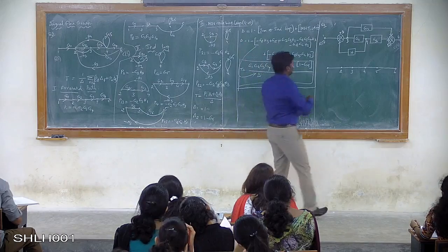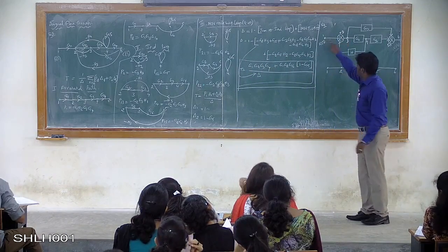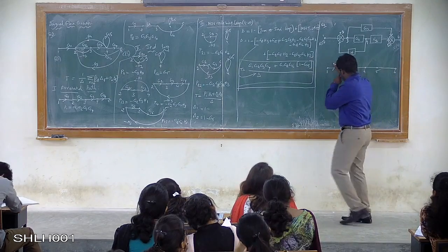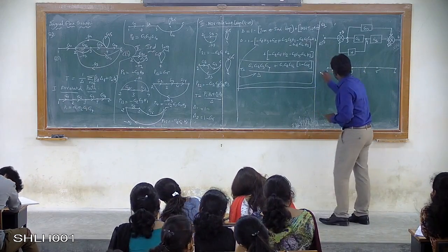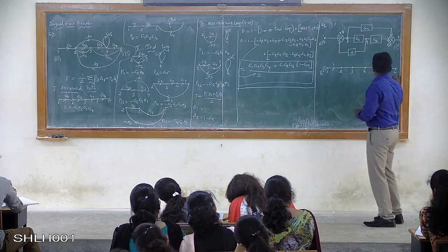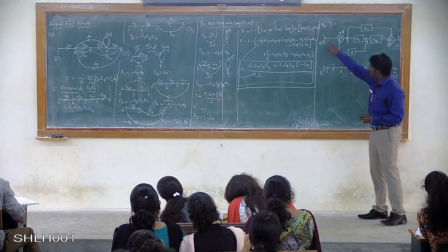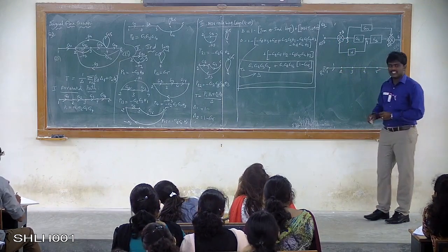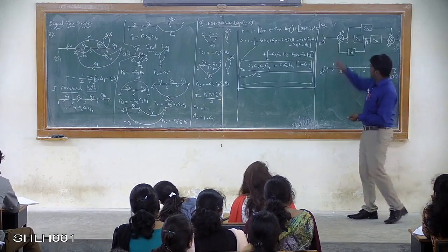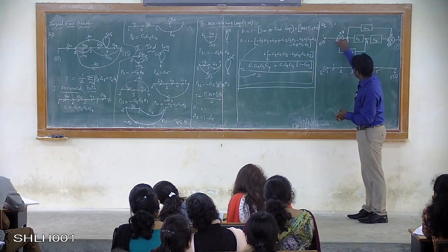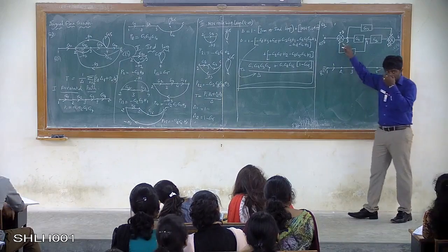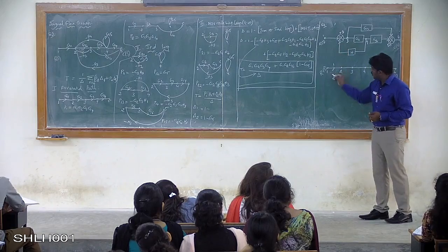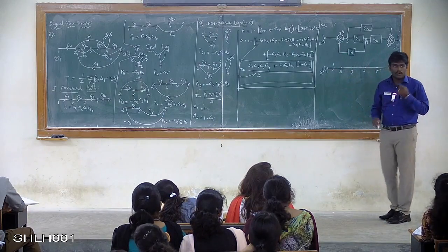Now, in between 1 and 2, right? What is the gain value? If anything is not given, you just take that gain value as 1. So this is R of S, then this is C of S. Between 1 and 2, you don't have any gain value given, so you take it as 1 from node number 1, and the direction is like this, right? Because from our input, it is given to a summing point, which is a set point. So you will have to mark the direction 1 to 2 like this.